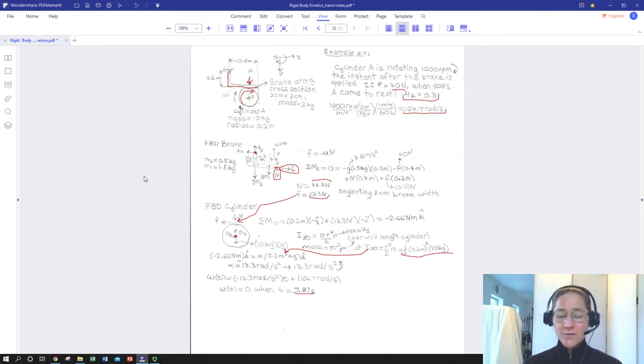looking at our expressions for angular momentum in terms of our product and polar moments of inertia, and then looked at which ones of those are non-zero for planar motion, and from that got our sum of the moments equals alpha times the polar moment of inertia, and then looked at ways we can leverage that along with other force balances and all of our kinematics that we've already studied for rigid bodies to write equations of motion based on force balance and moment balance to solve for the net necessary acceleration.